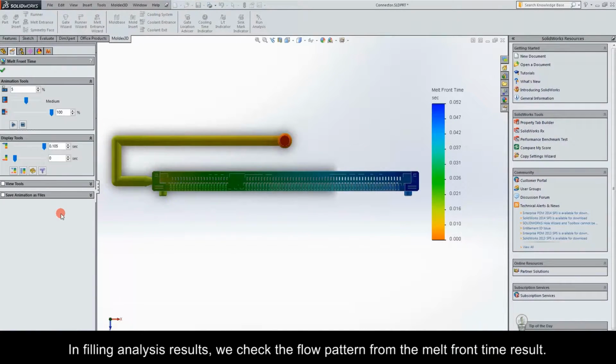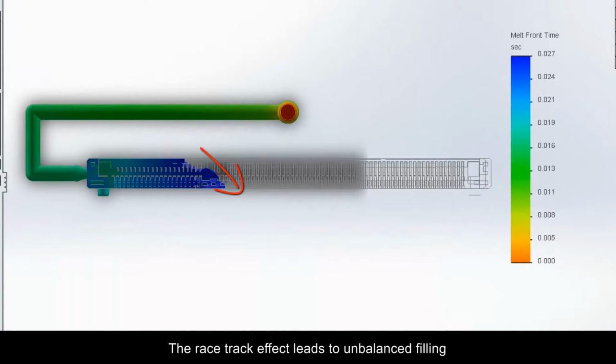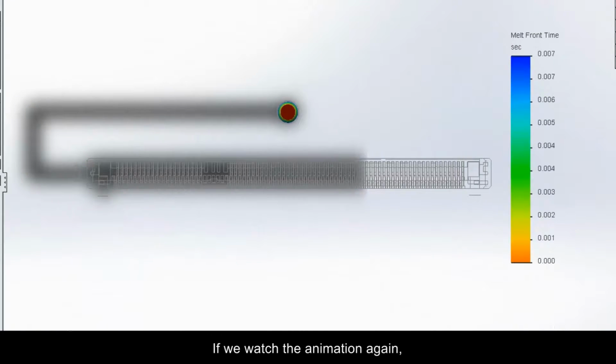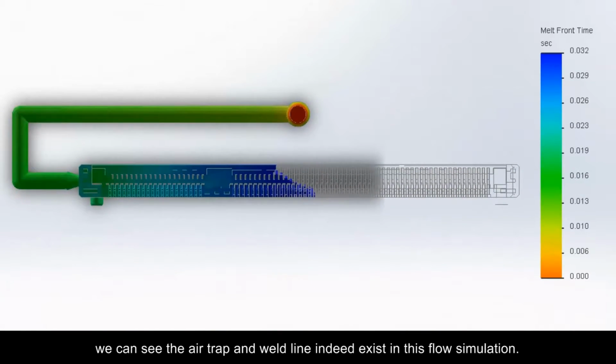In filling analysis results, we check the flow pattern from the melt front time result. It shows obvious racetrack effects in the filling animation. The racetrack effect leads to unbalanced filling and may cause uneven volume shrinkage, air trap, and weld line in the part. If we watch the animation again, we can see the air trap and weld line indeed exist in this flow simulation.